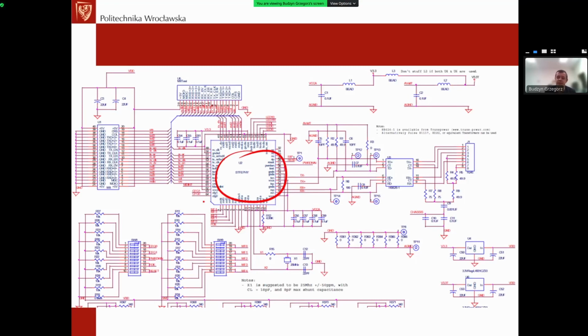So you can buy such a module that would translate some MII interface to the physical signals, either electrical or optical, of the Ethernet. But the cost of this chip is about 10 times higher than the cost of a similar chip translating USB to UART, for example, or to SPI. 10 times or even more. So this is a complex solution in general, difficult and expensive.